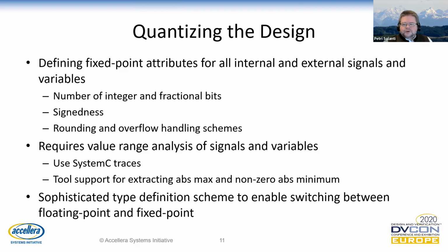The extracted fixed point attributes are transferred to the fixed point type definitions, centralized into a single header file for small and mid-sized systems, or subsystem-specific files in large designs. This enables switching between floating point and fixed point domains without editing the functional code.